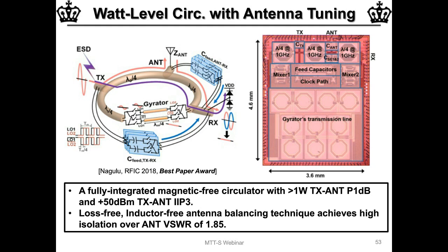But it is definitely true that at the end of the day, on-chip isolation or parasitic leakage paths through ground planes or substrate and so forth have to be considered. Again, any tuning circuit that you have helps because essentially these tuning circuits are canceling the leakage however it may arise, whether it's arising from a reflection at the antenna or through some parasitic leakage mechanism. It hasn't typically been a challenge to achieve more, especially in these circulators with these tuning circuits built in. We regularly achieve more than 40 dB of isolation over roughly 20% fractional bandwidth.